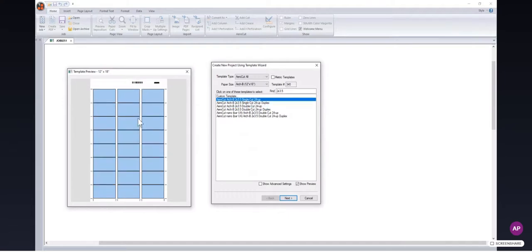You'll notice that there's a gutter here that no matter if you're doing single cut or double cut, you're always going to have this gutter, and that's one of the requirements. That's one of those inherent blade movement requirements. And what's nice is that this is already built into the software. You don't have to go into your graphic design tool and modify this or another imposition tool, which would make it hard to set this gutter up. It's already here.